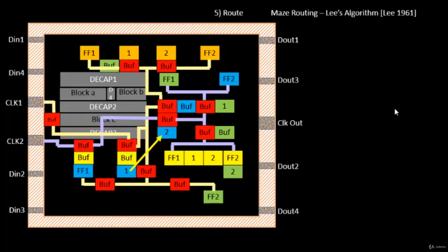Most of them should be L-shaped. There should be very few that are Z-shaped, and very few lines that are zigzag shaped. So we are looking for the best possible solution to connect between A and B. There are various methods to connect point A and point B, but we are looking for the best algorithm. From an algorithmic point of view, for the software, it is just two endpoints, and the software has to connect these two points. There are some search algorithms that it has to run in the backend to understand the best possible route between 1 and 2.